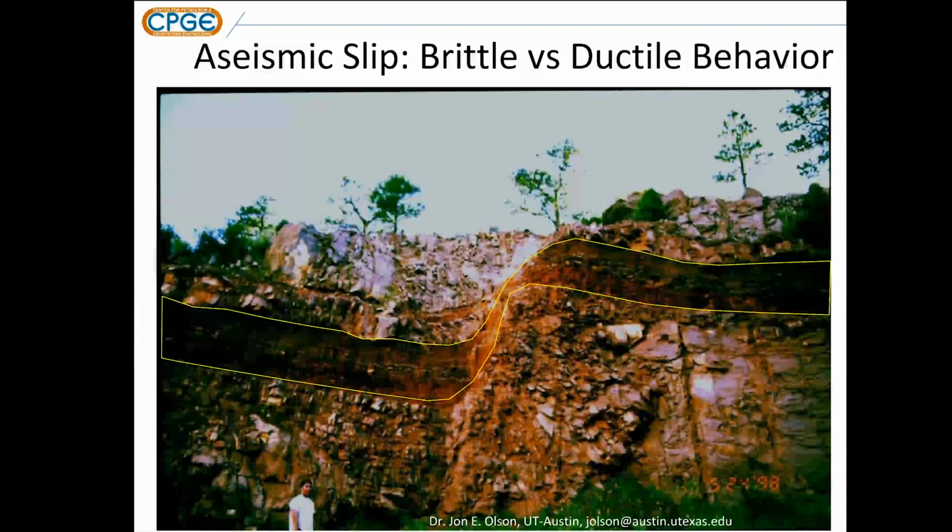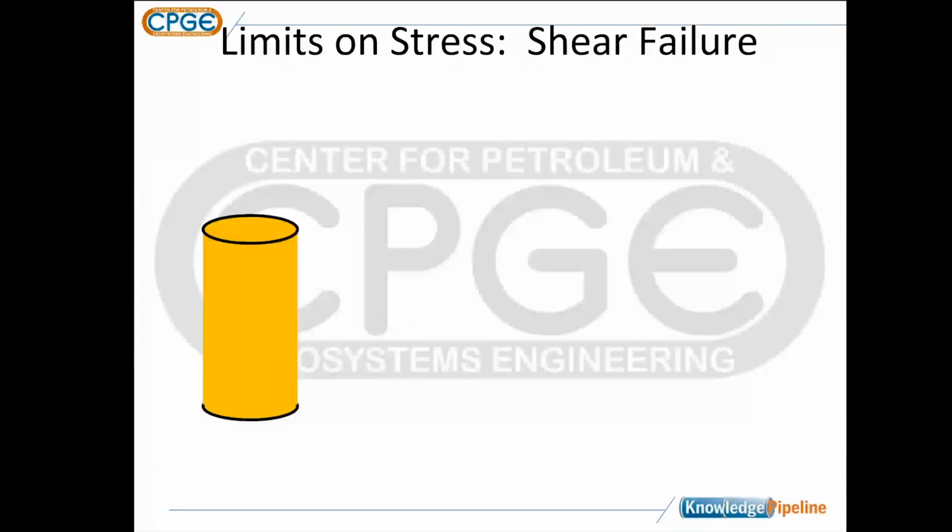So just a little bit about the mechanics then. And this is something some of you, I saw on the list, have sat through in my geomechanics class. The way we look at this and do the prediction part of earthquakes would be to say, let's go to the laboratory. We've got a core sample. We put some confining stress on it. That'll be the x-axis on my plot. And I call that S3, which is the minimum stress.